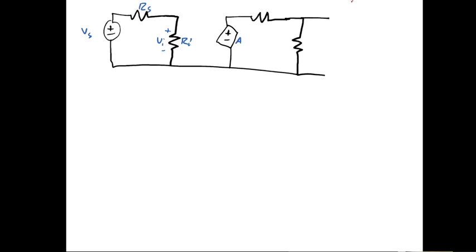And then we have a voltage-controlled voltage source which has a gain, the open circuit voltage gain, AV0 we might call it, times VI. And VI is this voltage we see across here. So magically it comes over and powers this voltage source. It gives a value times the gain. And then we have an output resistance to the amplifier. And we can show the load. And then we have an output voltage.